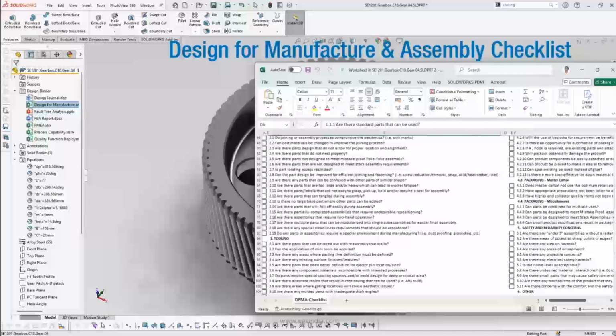Why is that a requirement? If a standard part is used in an assembly, the reliability goes up many-fold. Why? Because the history of the product is already known. So if we try and use as many checklist items as possible, and if we give due diligence at the design stage, those criteria which could have slipped through the fingers would necessarily get emphasized as a part of the process.